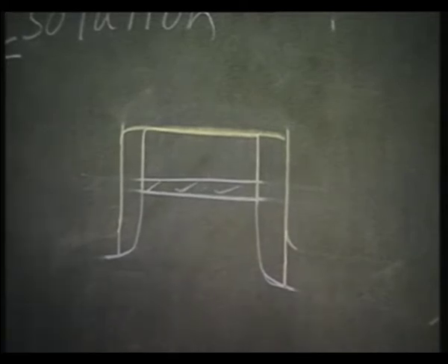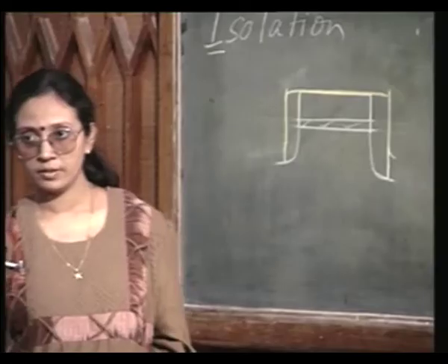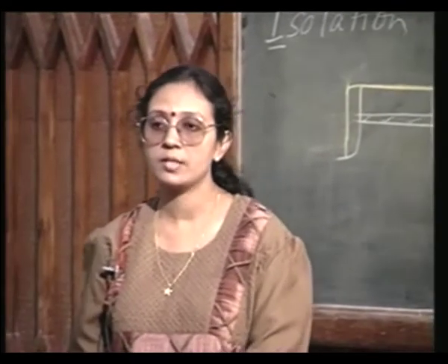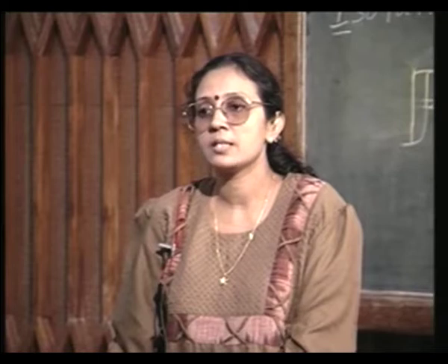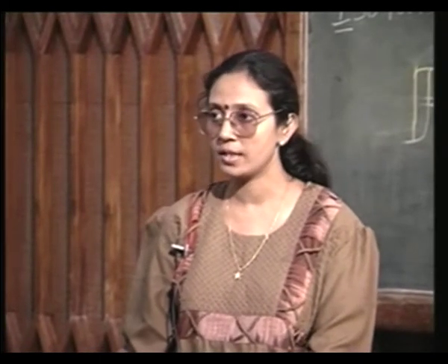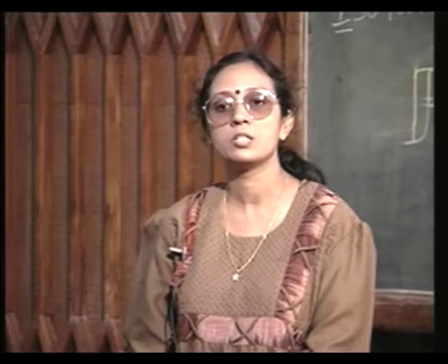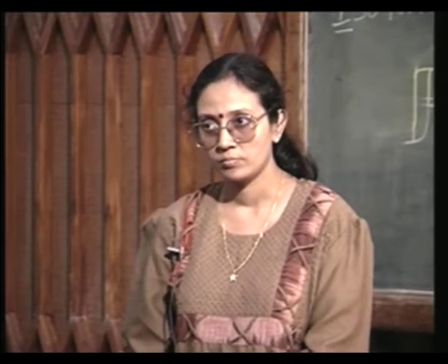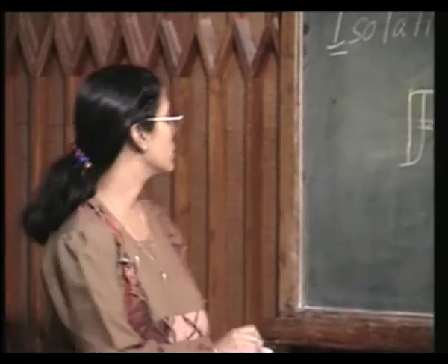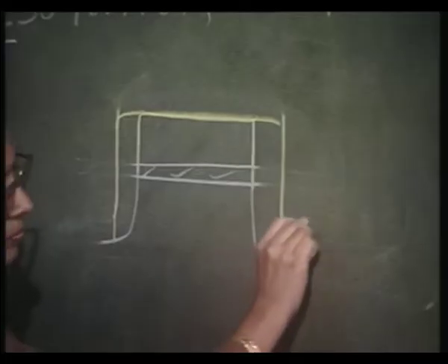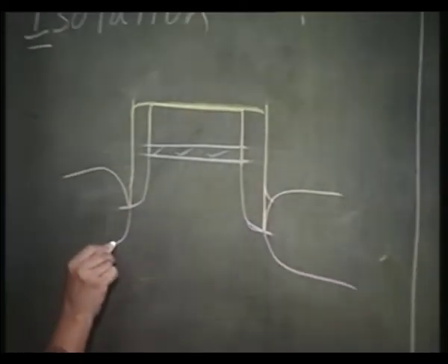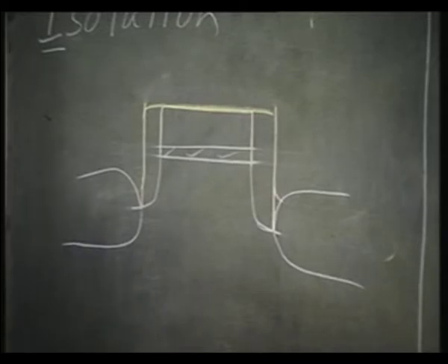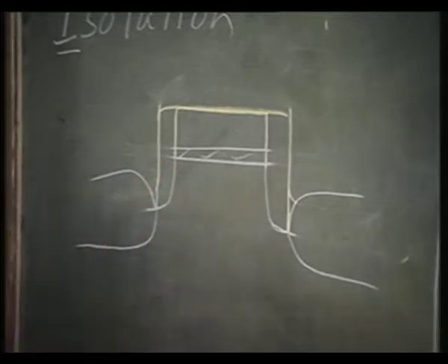You have just removed half of the silicon nitride, that is only the second layer of silicon nitride you have removed, but now you are using anisotropic etching so that the silicon nitride is retained on the side walls and only removed from the horizontal surface. Okay. So, now when you subject it to oxidation, even the side walls now are protected by silicon nitride.